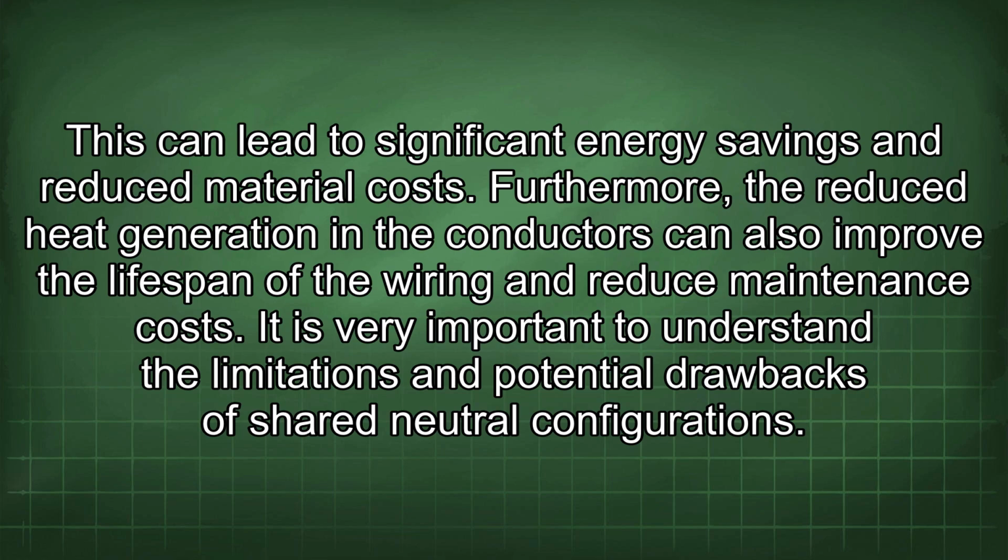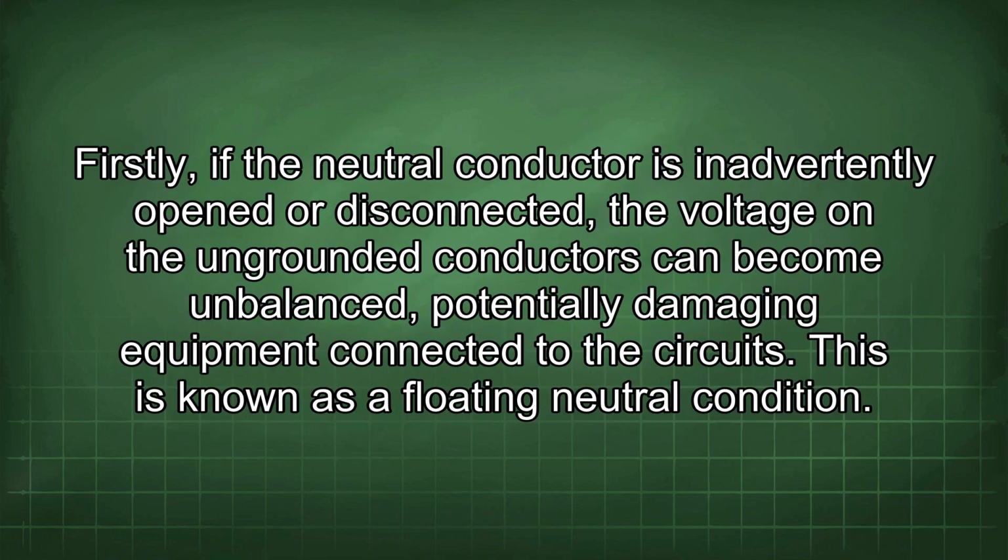It is very important to understand the limitations and potential drawbacks of shared neutral configurations. Firstly, if the neutral conductor is inadvertently opened or disconnected, the voltage on the ungrounded conductors can become unbalanced, potentially damaging equipment connected to the circuits. This is known as a floating neutral condition.